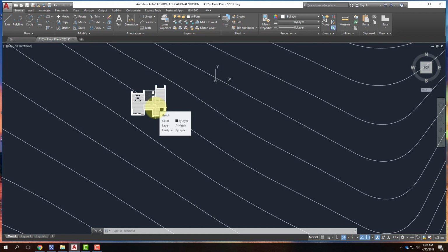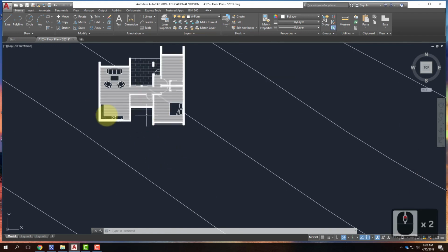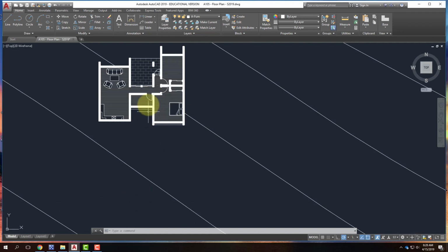We start to work with one drawing and bring down lines and guides and draw the related drawing next to it. So I'm going to draw the elevation of this right down here below my floor plan. So I take my floor plan and I'm going to draw the elevation right below it. So before I start drawing the elevation, I'm going to create a couple new layers.